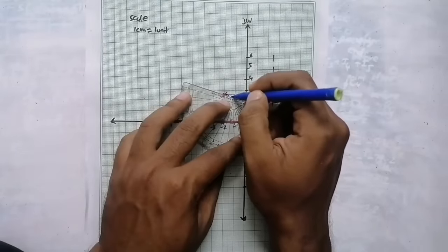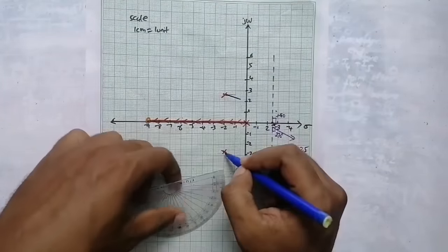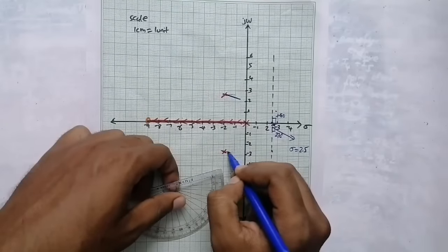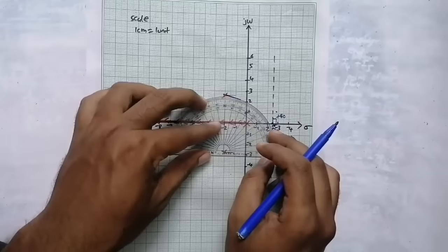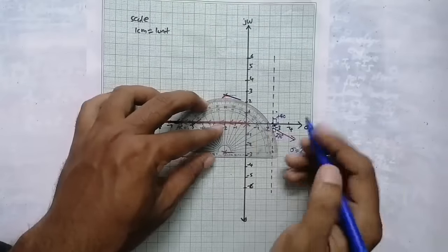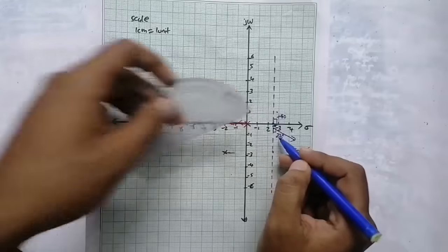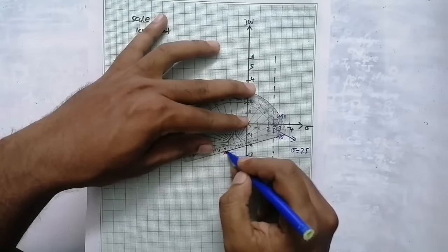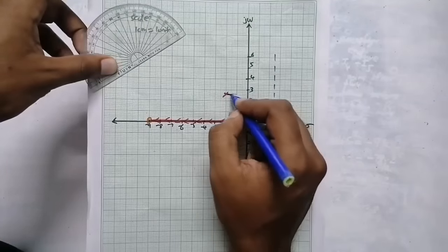Okay, 17 degrees. And for this complex pole, if this is minus 70, for this pole it is going to be plus 70. So again draw the reference line. Keep the protractor here. Then draw plus 70: 0, 10, 15 and plus 70 here. So this is the reference line. This is the angle of departure. Here it is plus 17 and here it is minus 70.